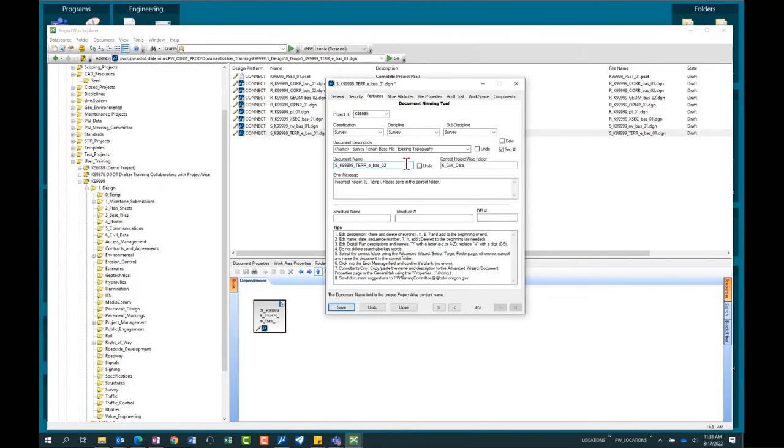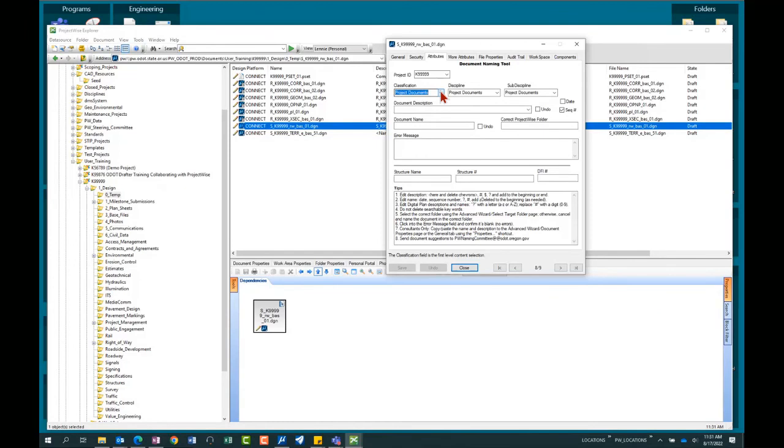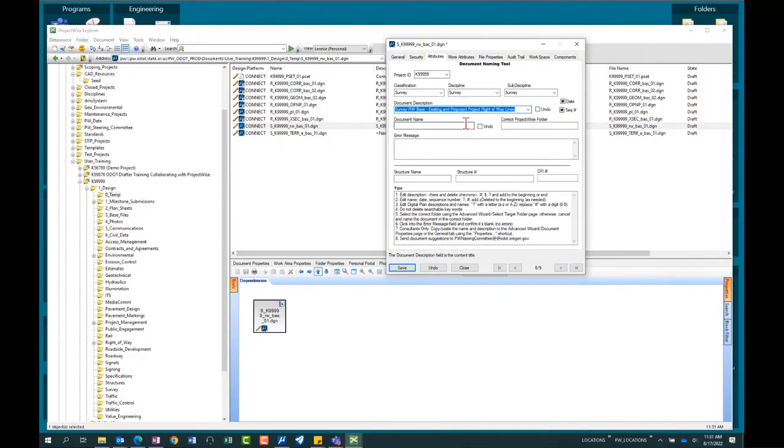I'm also going to use a naming convention for these files, and I'm going to start with the number 5. So this is going to be ebase51.dgn, and I'm going to click Save. Now, I'm going to leave the Properties dialog open and just simply select the right-of-way base, and then I can describe the right-of-way base. I don't have to keep opening and closing this Properties dialog. Oh, the right-of-way base is, there it is. It's at the top. Again, I'm going to rename this to a number that starts with 5. It's going to be 51.dgn, and then I'll click Save.